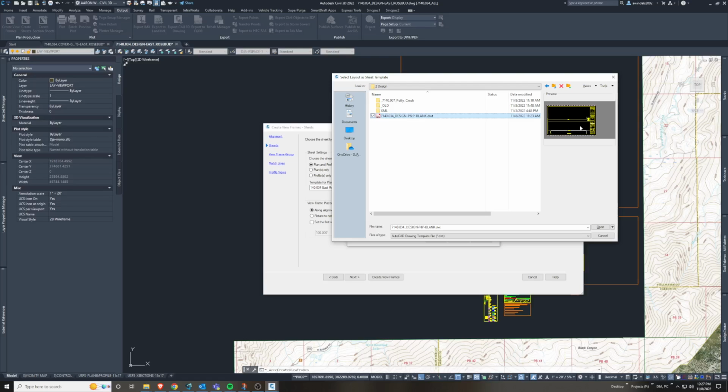These sheets are going to be created automatically, starting with view frame groups. On the bottom, it has a little mass haul area. So that was the main impetus for creating these slightly different: I wanted to leave a little void area on the bottom for the mass haul, and so it had the right spacing. And I didn't want to put another viewport right there either. I've never tried that with 3 viewports. I didn't want to freak anything out in the view frame group creation and then making the sheets after.